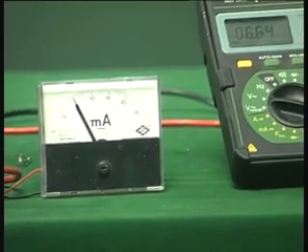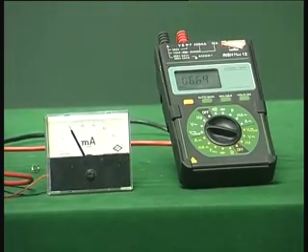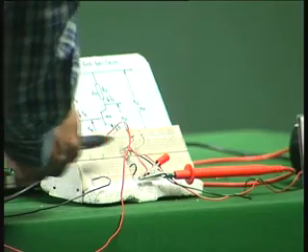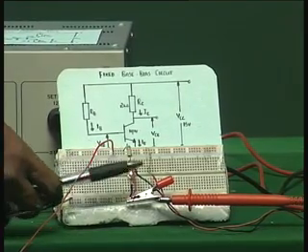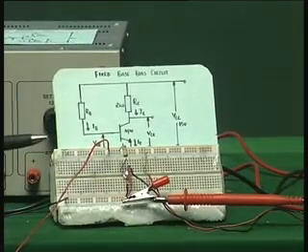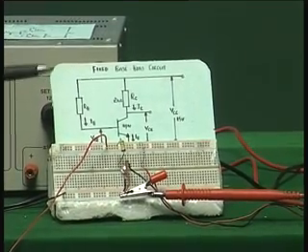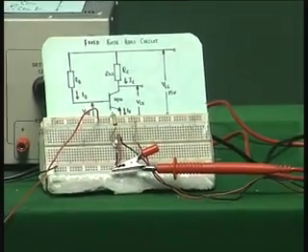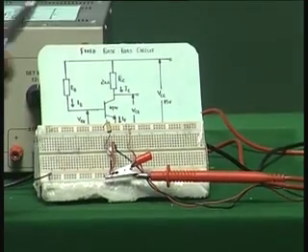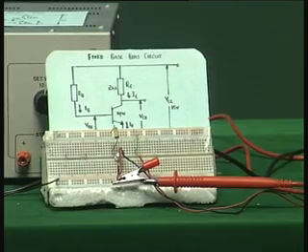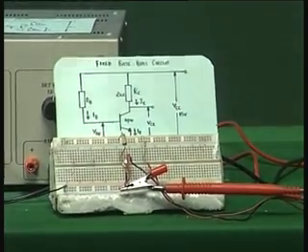You find the voltage and the current are very close. There are some changes. For example, instead of 6 volts, you are getting about 6.6 or so, and that is because these resistors have got some tolerances. As we all know, it may not be exactly 820 kilo ohms, and this 2 kilo ohm may not be exactly 2 kilo ohm, etc. So due to small variations in these, you are getting slightly different values of voltage or current, but this is quite possible in any given amplifier circuit, and these small variations in general will not make any great variations in terms of the performance of the amplifier.